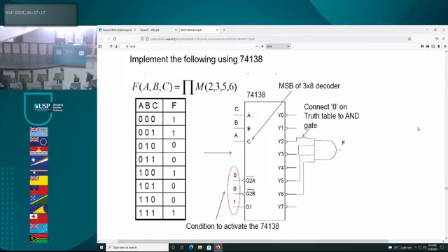you want to combine, let's take it one step further. You want to build a 3 to 8 decoder, but all the technician has is lots of 2 by 4 decoders. So these lines here, what you call the control lines. So these are your address lines, these are your output lines, these here are your control lines.